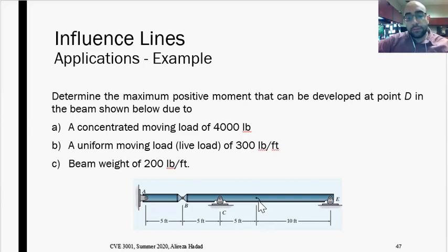So I'm going to consider a hinge, moving it up, and then I'm going to see a kind of mountain shape over here. At point C, we have to have the deflected shape at this specific point because we have a support over here. So this specific point is not going to experience any displacement.